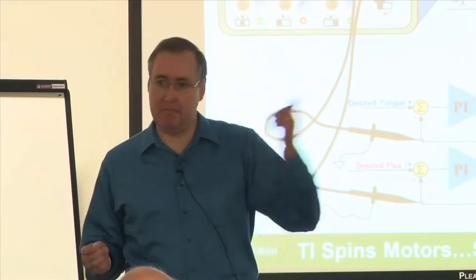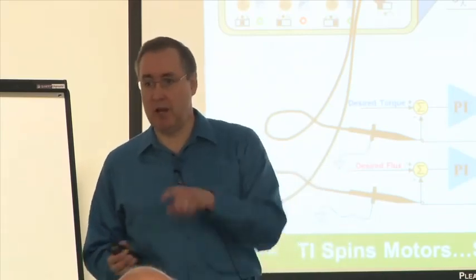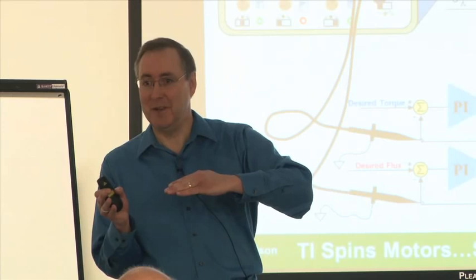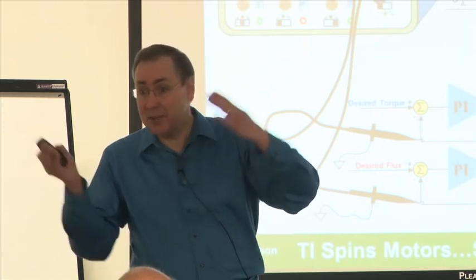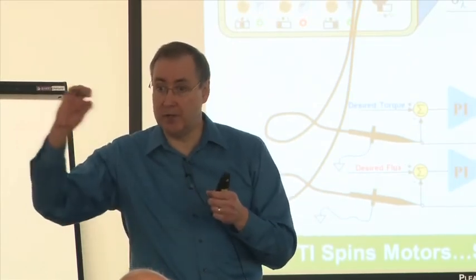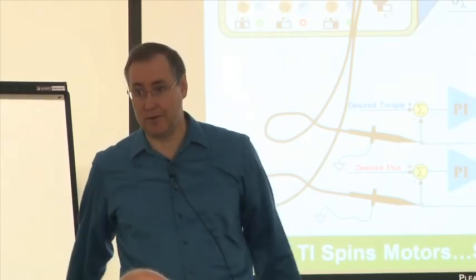You need to get the motor spinning, and you spin it manually just by applying a rotating vector on the motor. Now keep in mind that's going to be a very poorly efficient operation, because the rotor is just going to naturally want to line up with your rotating current vector, which means most of the current is going to be on the d-axis. But that's okay because you just want to get it moving. Once it gets moving, you're running your angle observer concurrently, and once you see that it's converging, you say it's started. We can now convert over to the field-oriented routine and turn off the starter algorithm. Does that make sense? How long it takes depends on how long it takes to get up to speed before you can start getting good angle information.